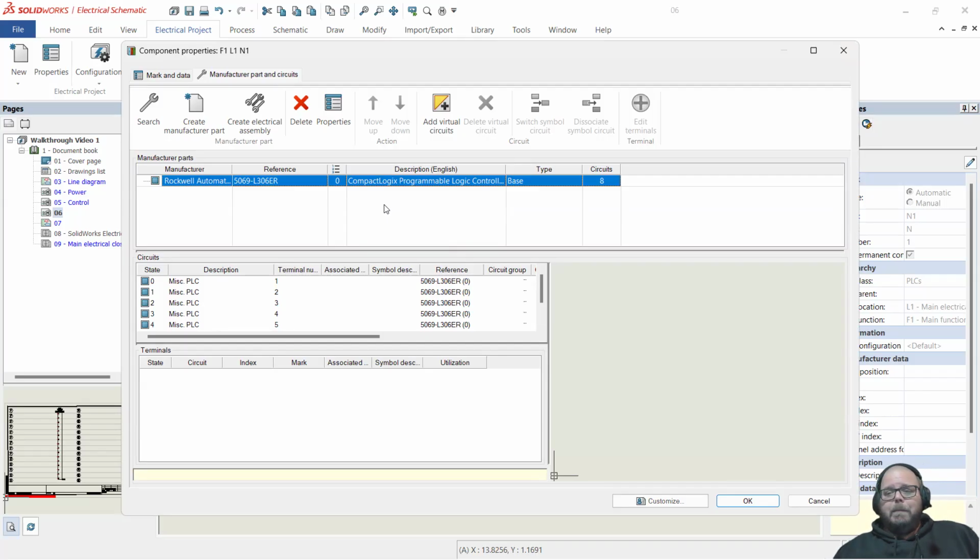They come with a bare connector on the face of them that you can connect a power terminal to, but when Allen Bradley switched to this family of PLCs, they don't come with power terminals anymore. You have to order the power terminals as a separate line item. So we need to account for that, if we are creating this to generate a bill of materials ultimately that we're going to order off of, to make sure we're not missing parts. We need the power terminals in here specifically for this PLC.